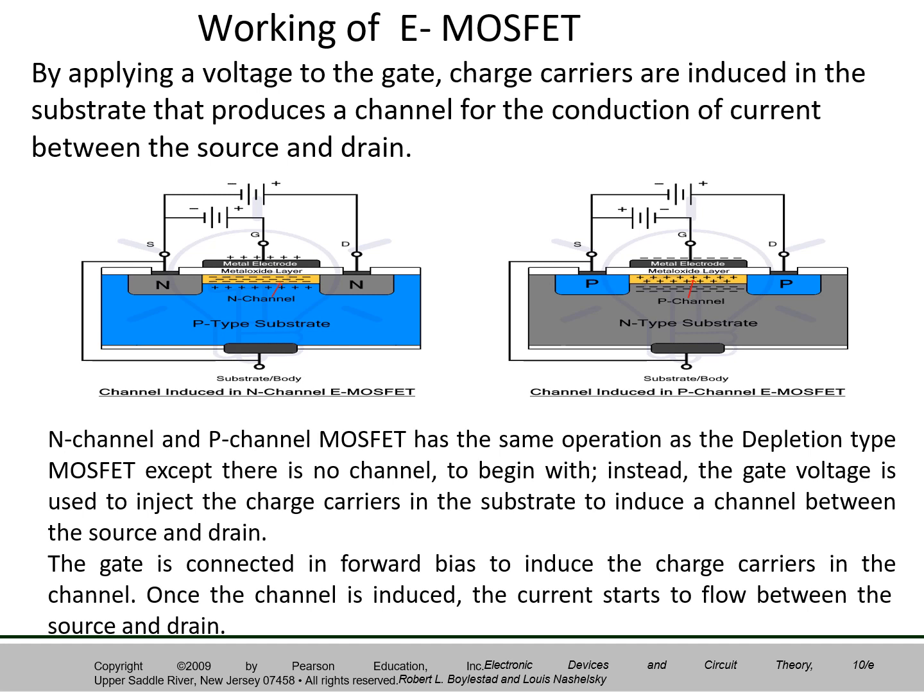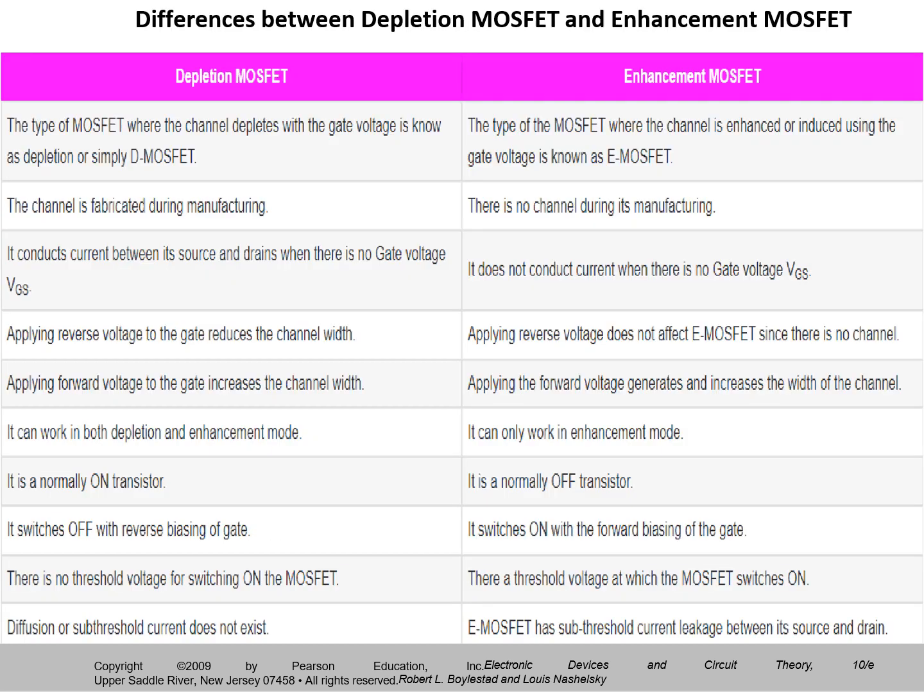That concentration of electrons increases as you increase the value of VGS, which is nothing but ID increases. The level of VGS that leads to significant flow of ID is referred to as threshold voltage, which will be marked in the characteristics here.